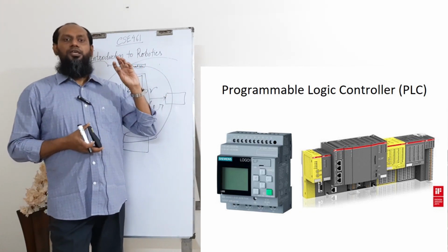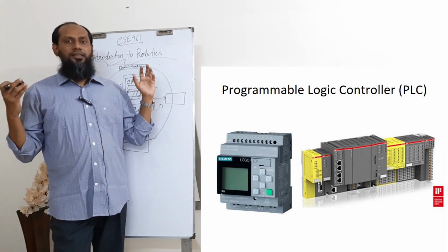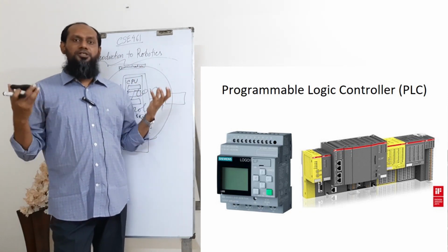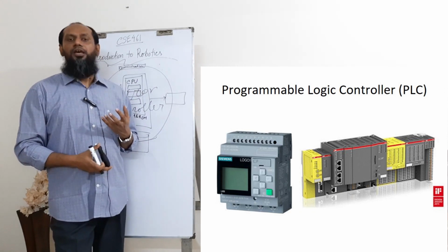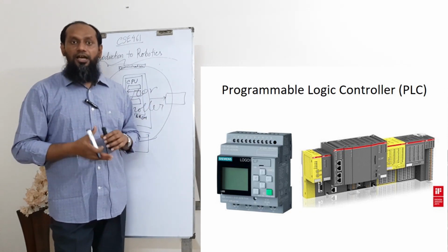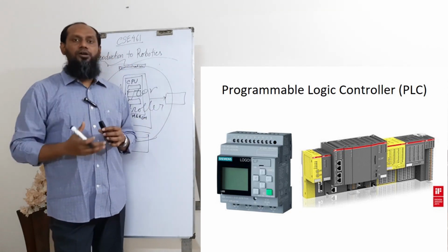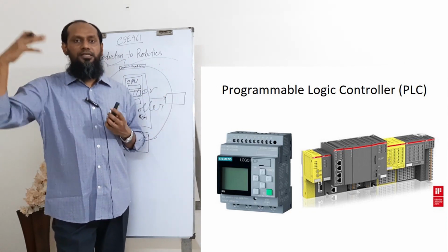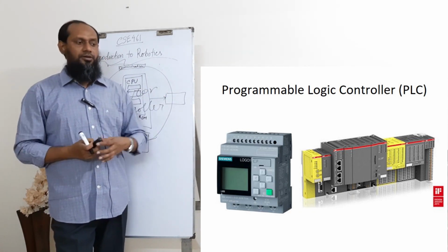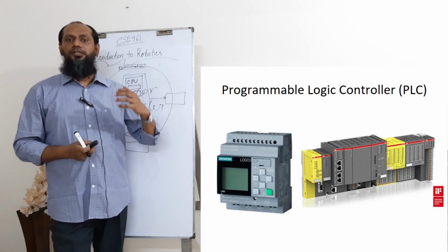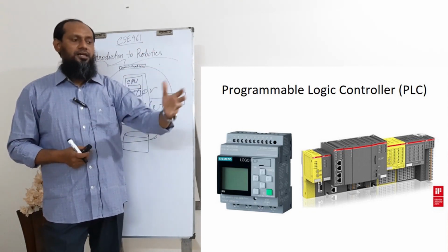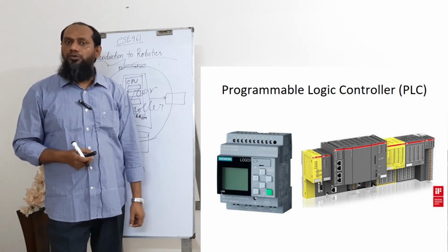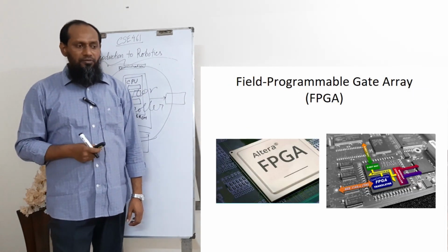Okay, when you want to use some machine which will run 24 hours a day, 7 days a week, okay, 52 weeks a year, for that kind of machine, or in a very rough environment, okay, in the sunlight or even in the rain, okay, for that kind of purpose where the temperature fluctuates a lot, in those circumstances, PLC can be a good choice.